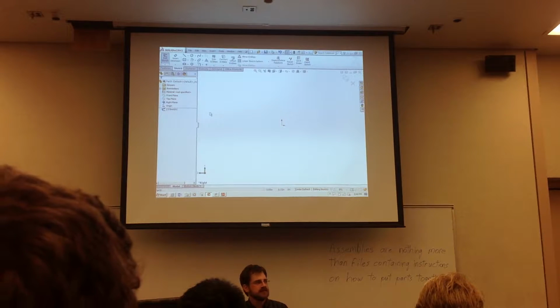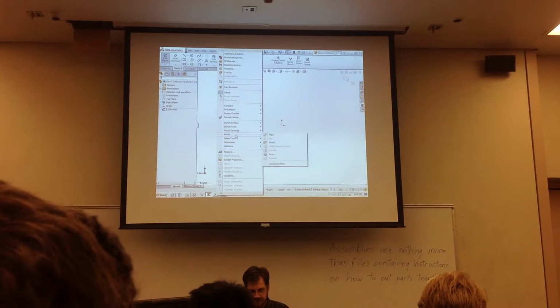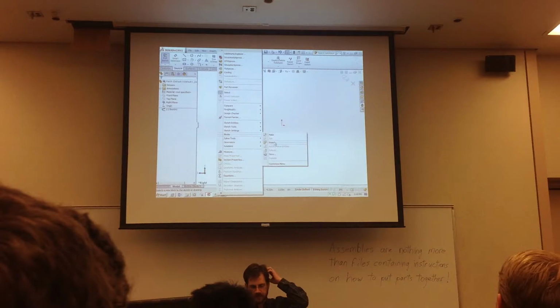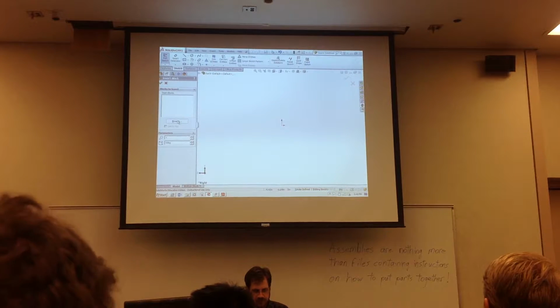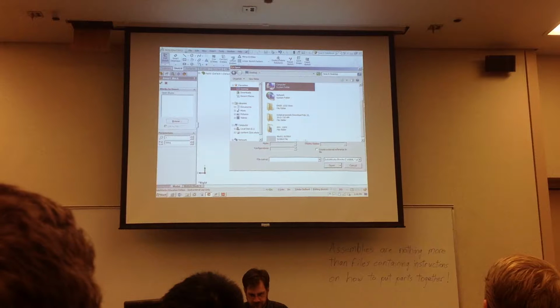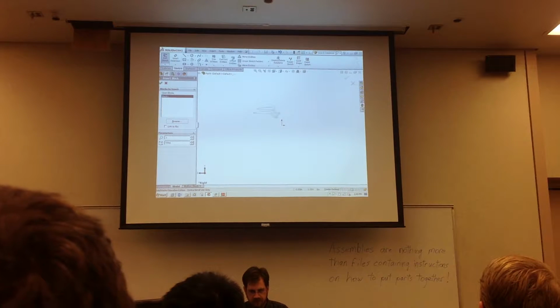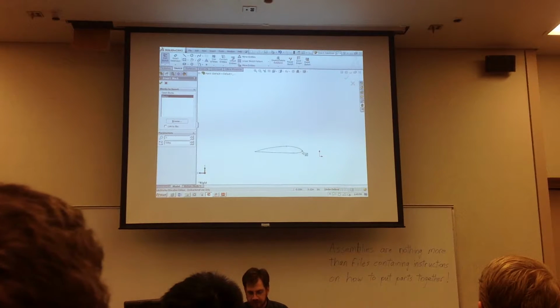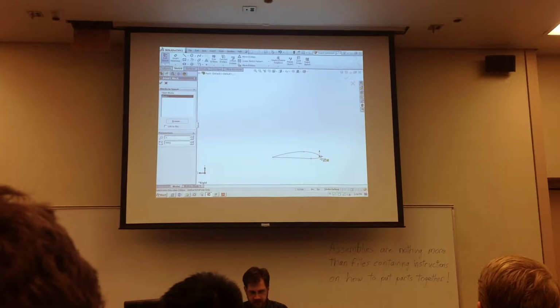Now to bring the sketch block in, we go to Tools, Blocks, and Insert. Click Tools, Blocks, Insert, and then browse to find the block that you want. It's on the desktop, and I should be able to find block 1 right there. Say Open. And it follows my cursor around. Notice it's the insertion point that's following my cursor around. And if I want to snap that to the origin, I can easily just place that right there.